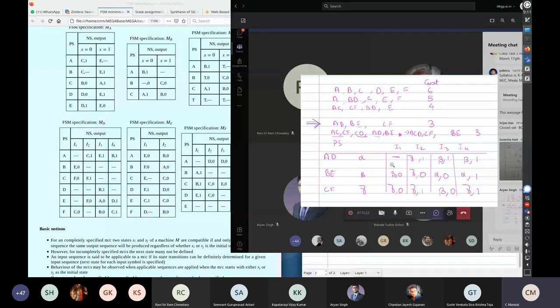And the next state, if I1 and I2 are adjacent, for example, you might like to put it as gamma, because when you minimize the functions, keeping it as gamma is likely to be easier to simplify, or the cost of implementation could be reduced. So as compared to alpha, gamma might be a better choice.